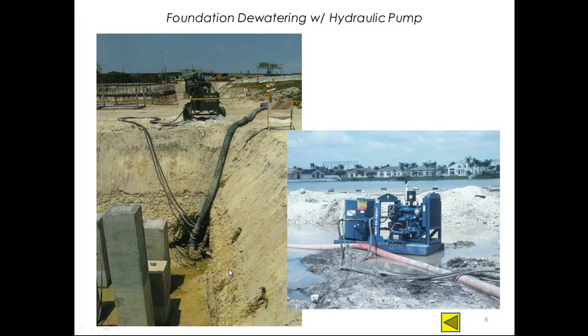The pump gets its name because it is powered by a remote power unit hydraulically. The hydraulic fluid then under pressure flows through these lines. It turns the pump head, and the pump then intakes the water and pushes the water out through the discharge line.